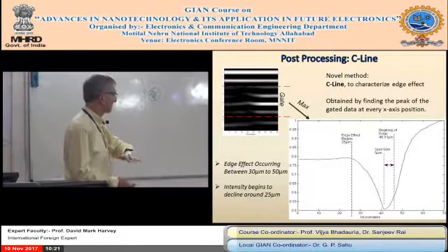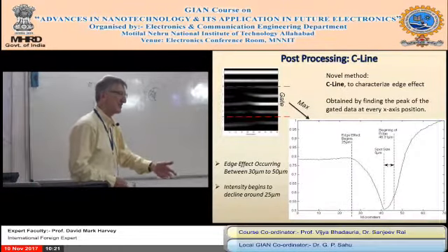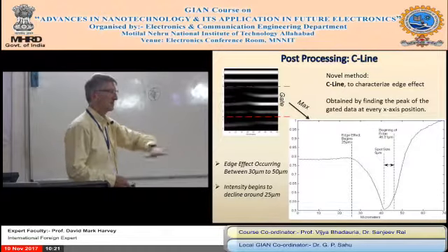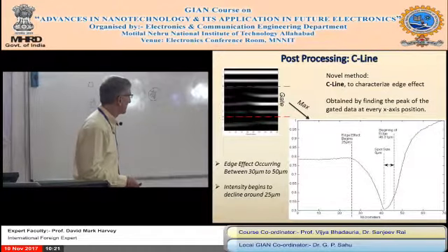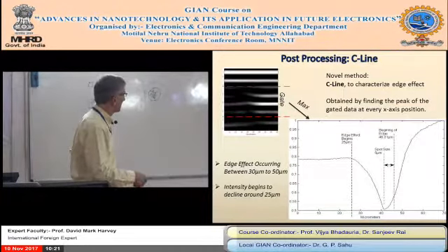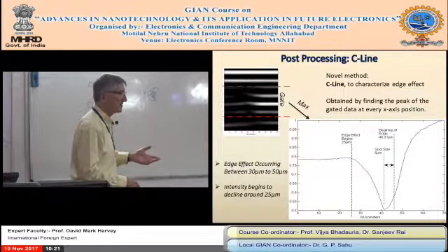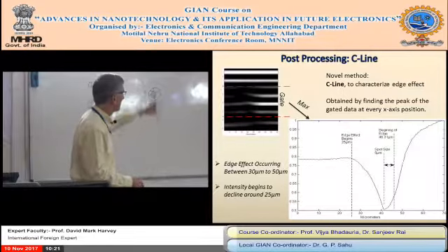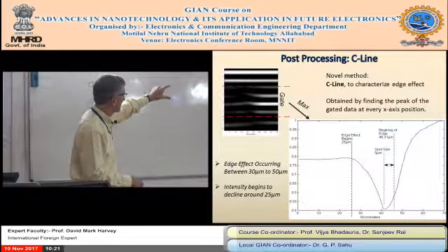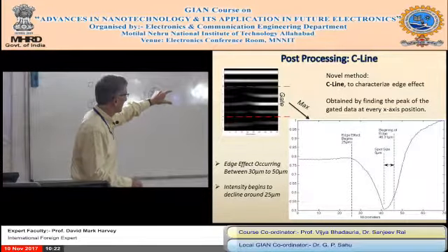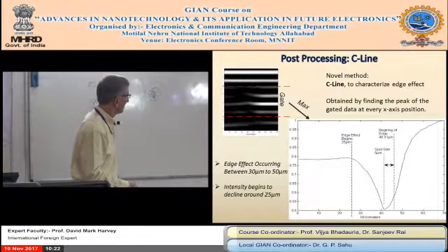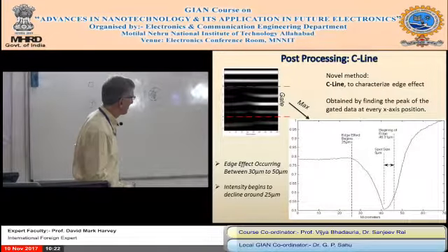And if you do that, you get what's called a C scan. There's a lot of ABCs in this. A C scan's a planar scan, as we'll see later. So he sets the gate. The gate's this big. This is a virtual gate simulation. Anything for the highest value in the x-plane, and then he plots it like this, and he gets this type of picture.